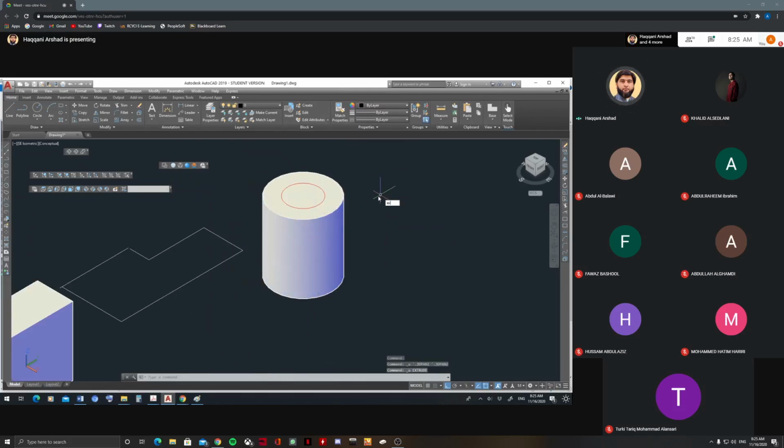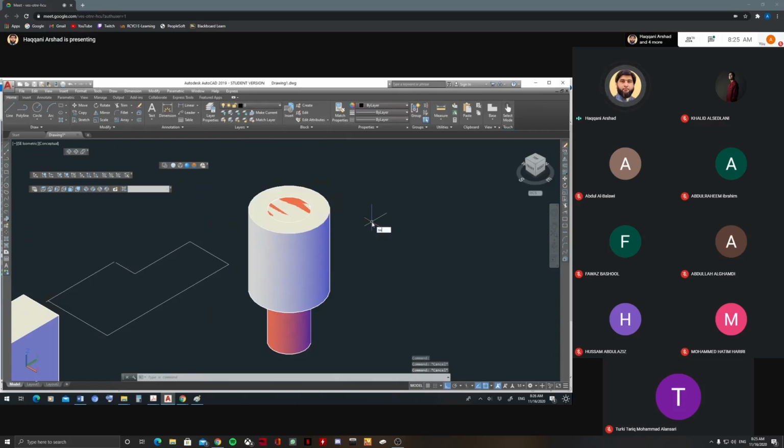I'll go for extrude this circle. Enter. I have to put like this. Now I can easily delete this one from this cylinder. So I have an option called subtract, meaning minus, because I have to minus this one from this. So for example, this is my hole. I want to subtract. So SUB, you have an option called subtract. Okay, remember this one is easy.